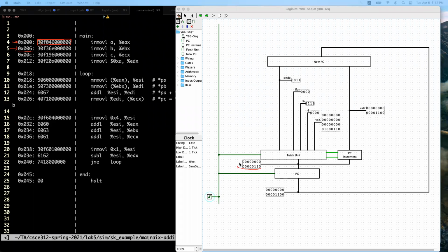So the next PC is this one, right? This is 16 bits. So then how do we read it? Like a hexadecimal number, we break this binary into 4 bits like this. And then this is 0, 0, 0, and 6. Okay, good. So the next PC value, the next instruction address, is 0006, and it is the same as this code.